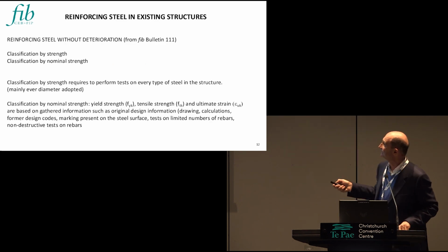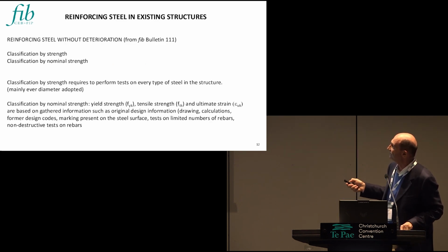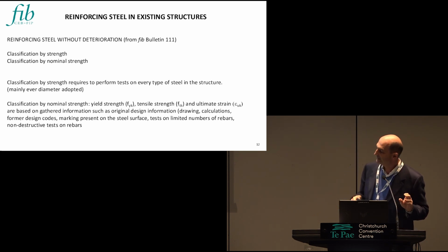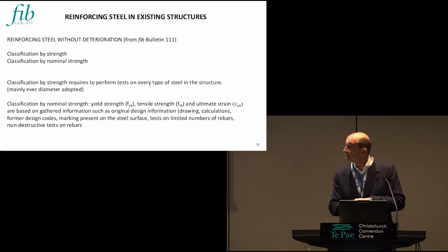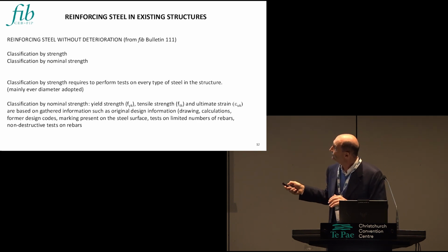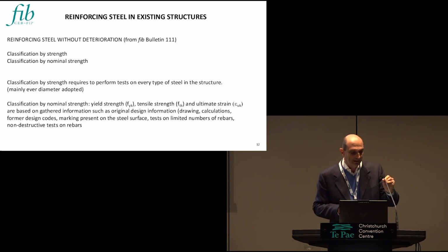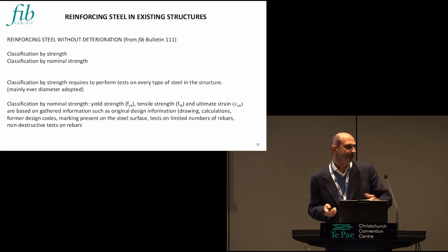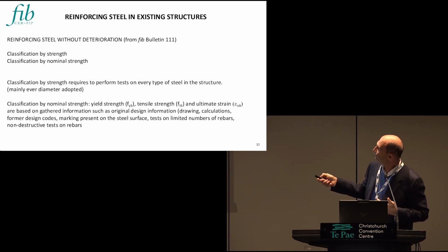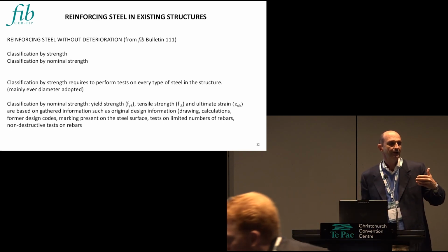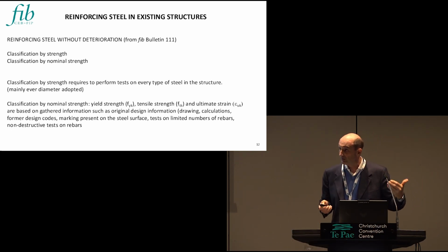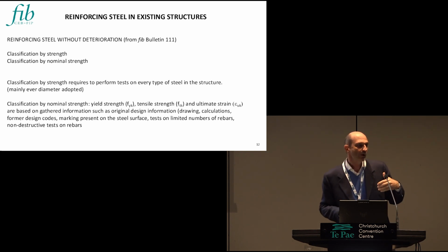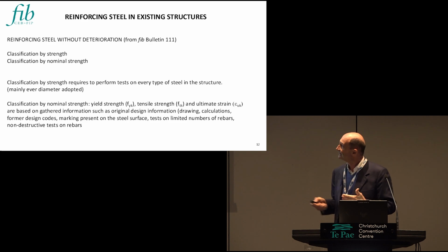In reinforcing steel without the deterioration, I would like only to point you to something that is clarified in Bulletin 111, particularly that we have two possibilities to classify the steel, I mean by strength: one is the actual strength we can measure on the structure, taking some sample and testing it, and the other is to use the nominal strength for which the structure was designed.